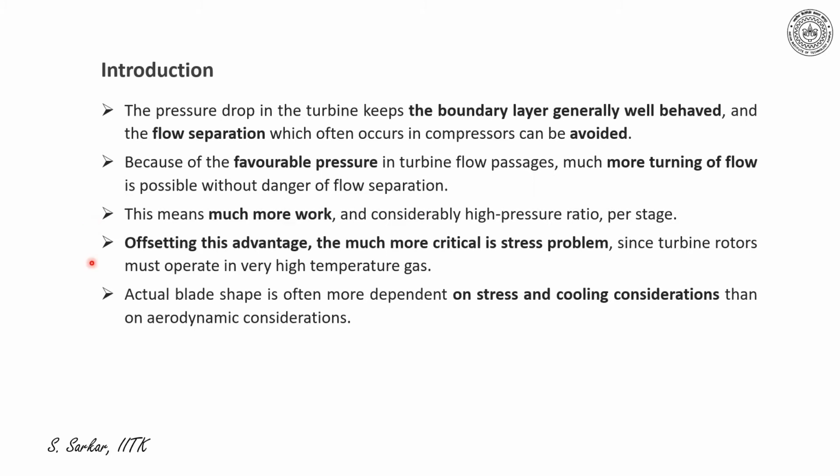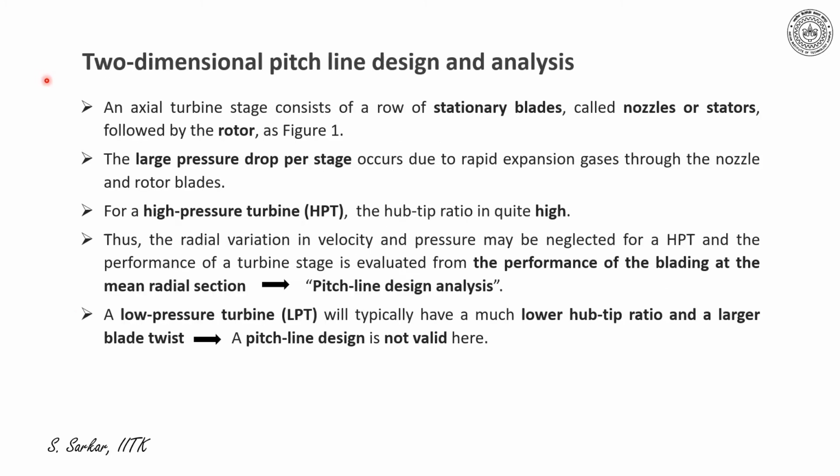Offsetting this advantage, the stress problem is much more critical, since the turbine rotor is exposed to high gas temperature. Furthermore, the blade shape here is often more dependent on the stress and cooling considerations than the aerodynamic considerations. I'll explain here the two-dimensional pitch line design and analysis.